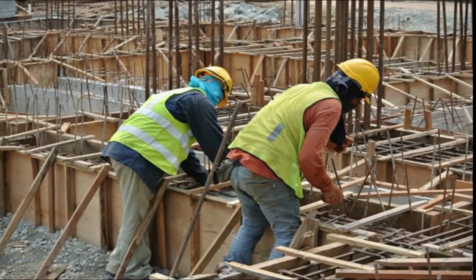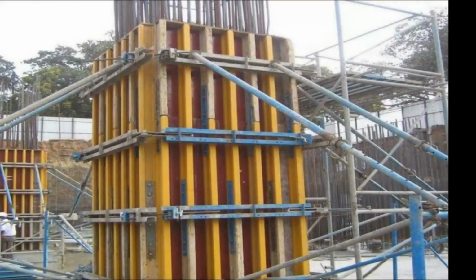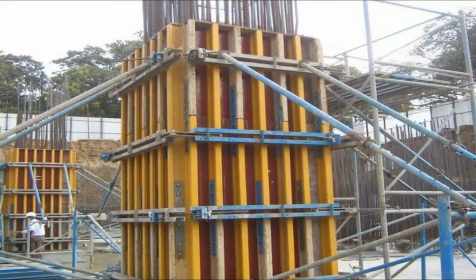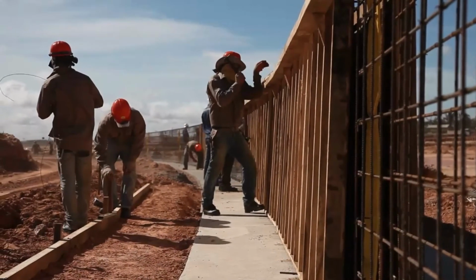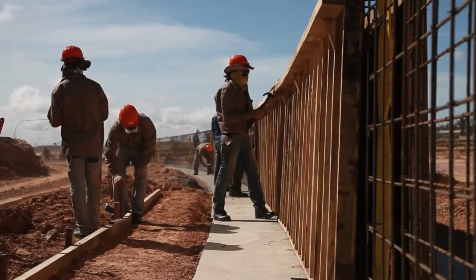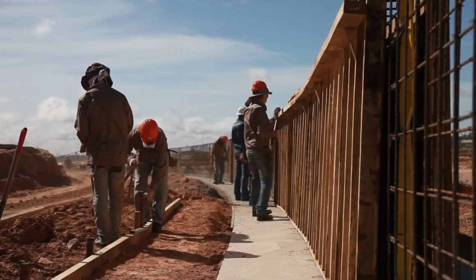Concrete foundation forms usually are made of wood. They also can be made of steel, or a combination of wood and steel. Wood is lighter in weight, easier to handle and less expensive than other materials. Also, it is easier to change the size and shape of wood by using hand tools, unlike steel.